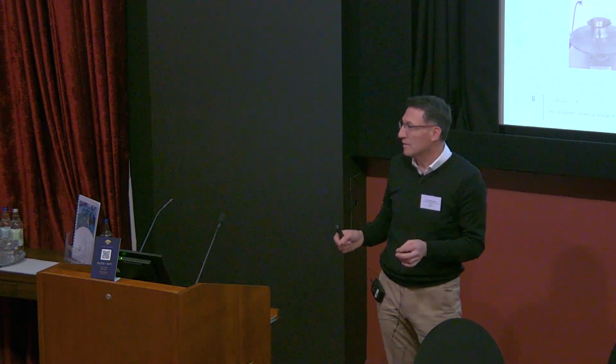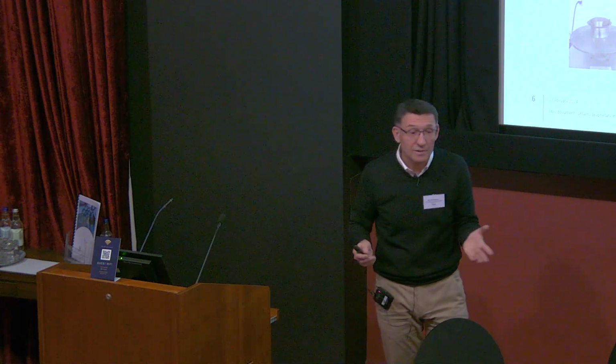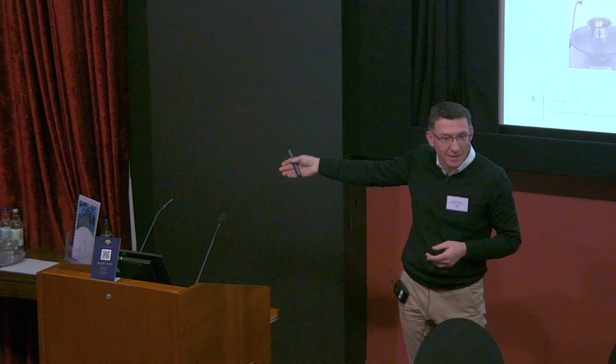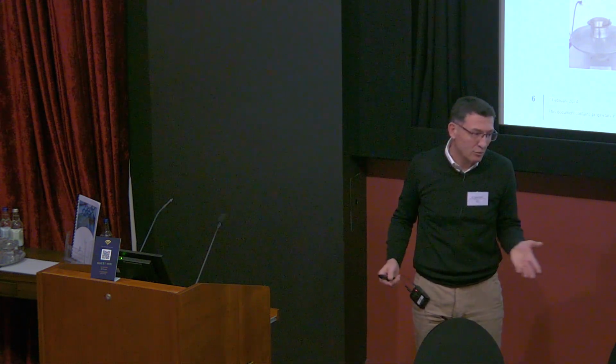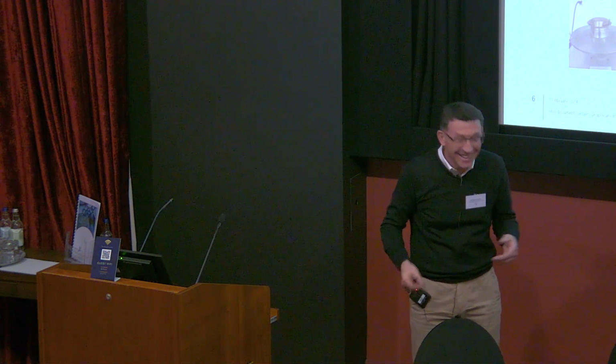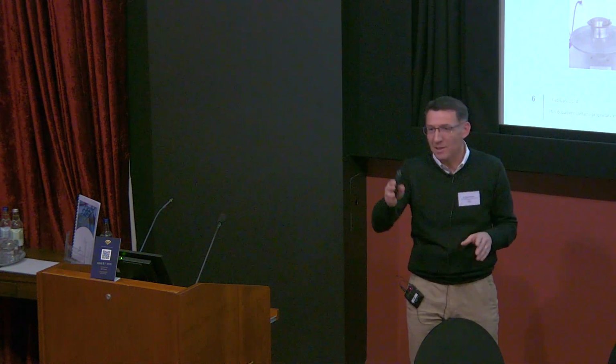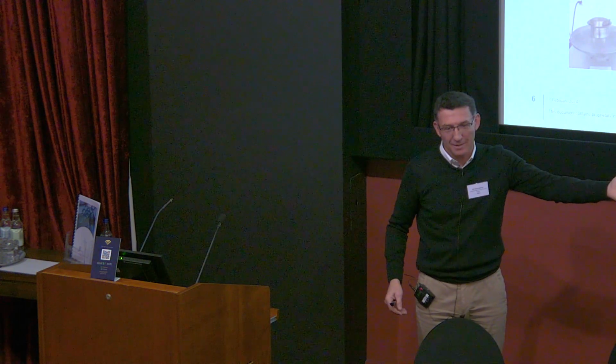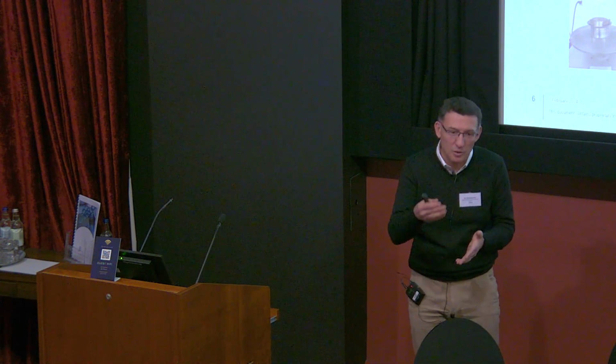So this is what we do. We optimize first the packing and the stability of the system with the GCC. Second step, where is the need of the customer? If we want to increase the strength, he can play with the superplasticizer. If he says he has enough superplasticizer, do you want to add more cement? No? So what can we do? We can propose some fine GCC to optimize the fine packing.